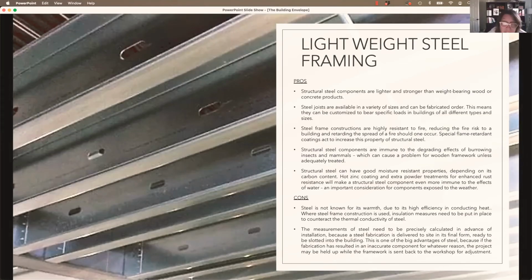I have a question in regards to if you're putting in like a larger bathtub that's maybe going to hold more than your regular standard bathtub. What sort of things and how easy is it to get to those studs to make them stronger to carry that weight? You might need extra bridging, or in a minute we're going to talk about floor trusses, which have extra structural support. And my guess would be you probably would use a floor truss in that space to bear the weight.